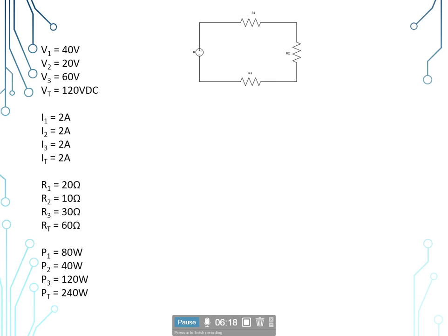So now this is all the calculations that we can find for this particular circuit. We're ready to go out and make our live readings of this circuit and compare them to this and see if it's close, real close, and we're good to go in that part of the circuit. If we're way out of the ballpark, we need to look a little bit closer at that component or that part of the circuit because we have an issue there.